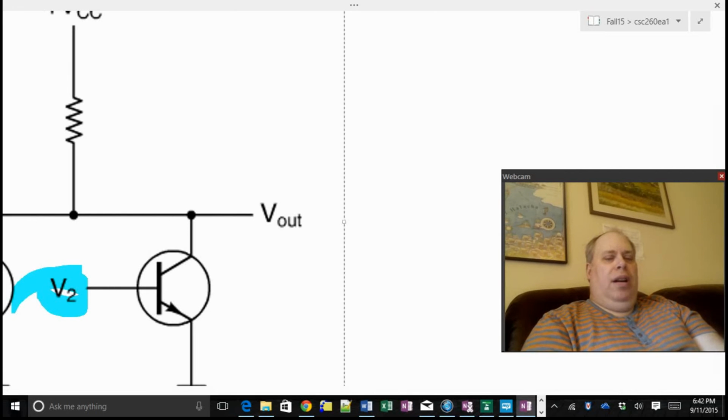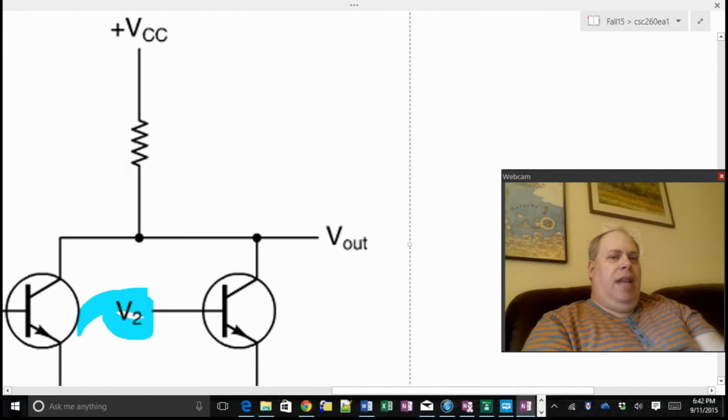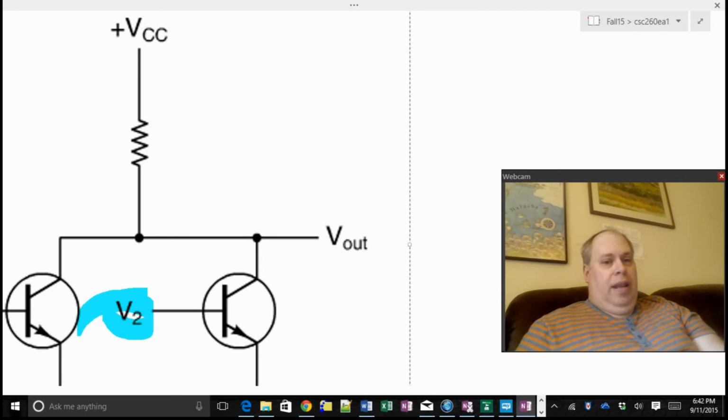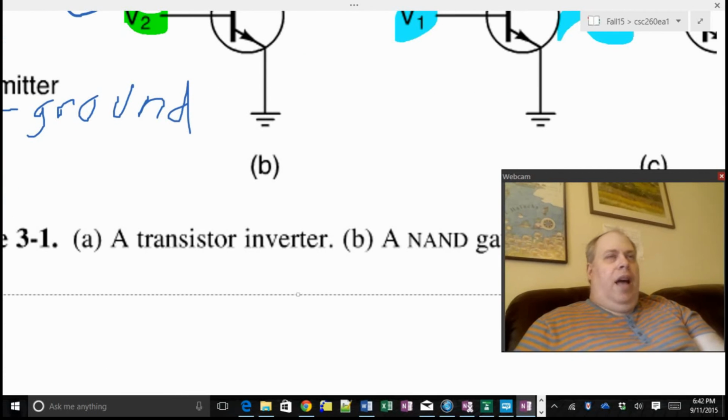So CMOS is a lot more complicated to make. It tends to take up more space on the chip, but power consumption issues are sometimes the most important thing. If you build the tiniest chip in the world and it immediately catches fire on use, that's not so useful. Other people have talked about this: the less switching in CMOS, at least, the fewer problems you'll have and the less heat you'll generate. So faster switches are better not only because they're faster, but because they generate less heat.